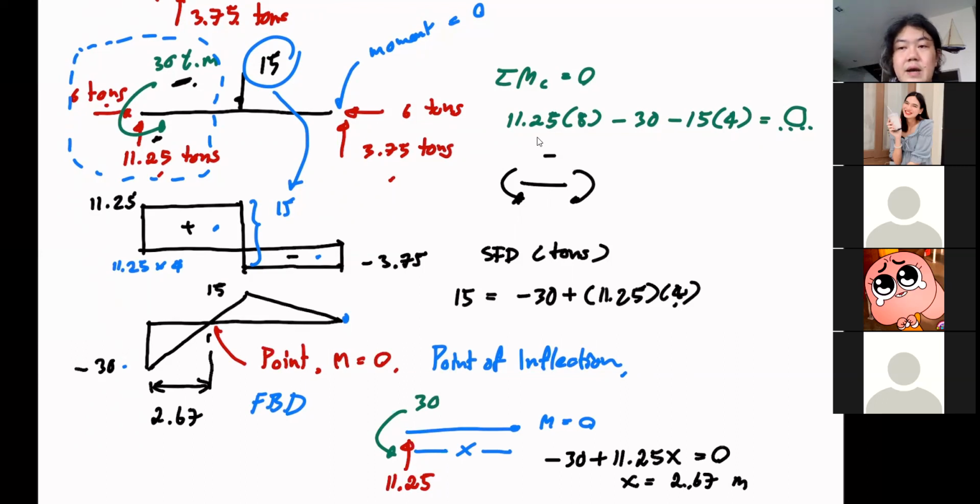The second thing that you need to be able to see from the bending moment diagram, thanks a lot for the answer from the chat, is how your structure is deformed as well. Okay, from the bending moment diagram, if you can recall the sign convention that you use, that is exactly how your structure is going to deform. It is going to deform exactly like your sign convention.